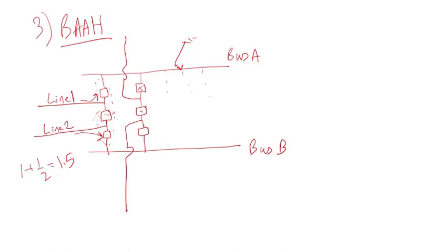Now what if this line here, for instance, is faulted to ground? That means these 2 breakers need to open to isolate the fault, including the breaker on the other side, but let's just stick with this substation. These 2 breakers need to open, but let's assume the middle breaker somehow did not open. Then it's going to transfer the trip to the next breaker, which means you're going to take another line out.